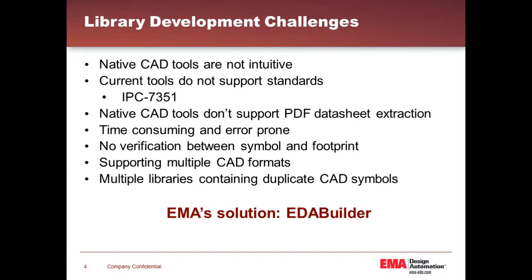Some companies actually, for creating the land patterns, would create almost a one-to-one pattern of the actual part itself, the chip itself, to determine what the ultimate pad should be to recognize the toe and heel dimensions. And again, that's a very time-consuming, laborious process.